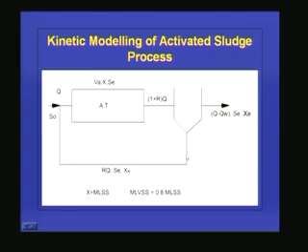A portion of the sludge will be recycled to the aeration tank. RQ is the flow rate, R is the recycling ratio, and SC is the BOD, because the same SC will be coming, and the biomass concentration is XR, because in the sedimentation tank the biomass gets concentrated and we are recycling the concentrated sludge.